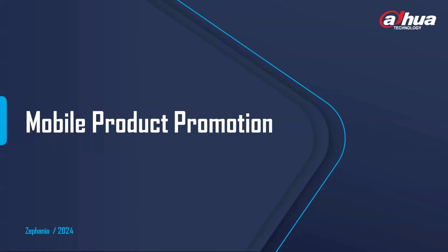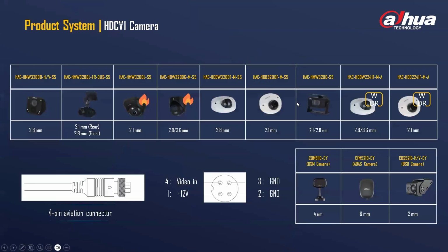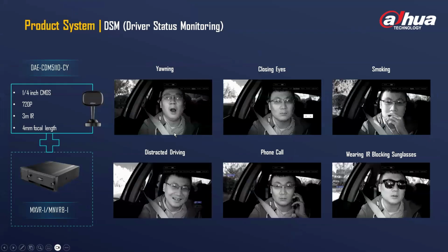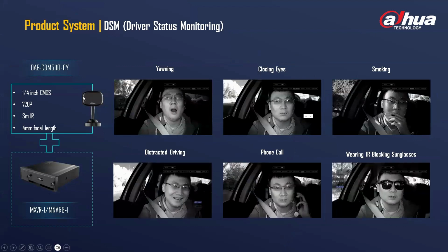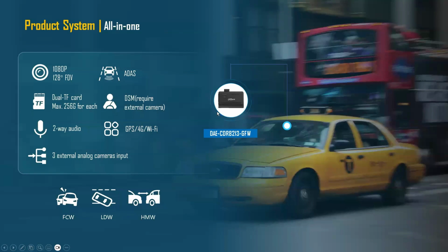Okay. So to respond to these questions about the DSM camera, I'll just prefer to go to it. Number one, the DSM camera is installed facing the driver. This is how it would look like. This camera, the advanced driver assistant camera, is facing the road, but you see the note is it requires a DSM camera to work efficiently, to do the DSM functionality.